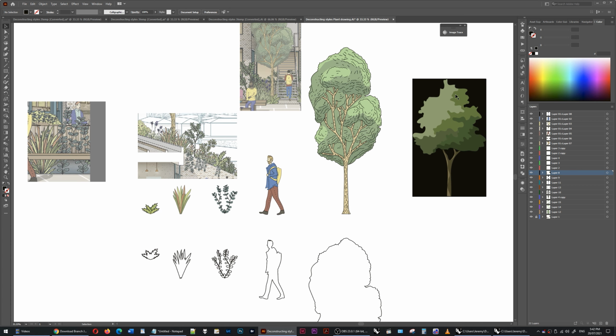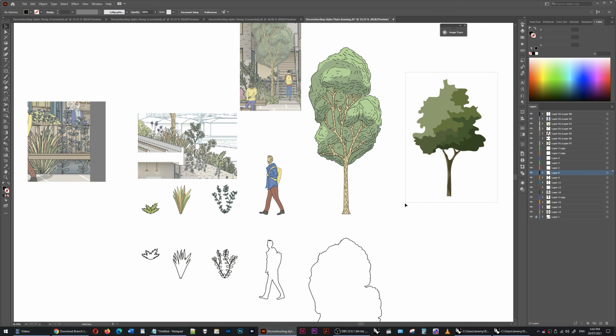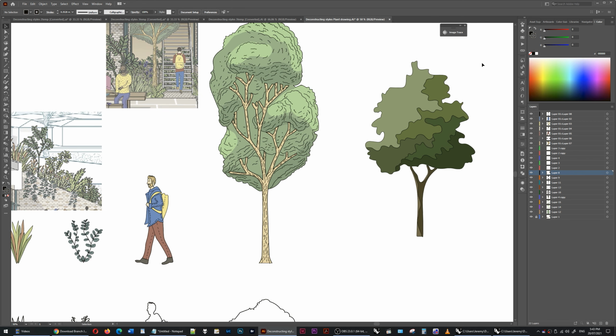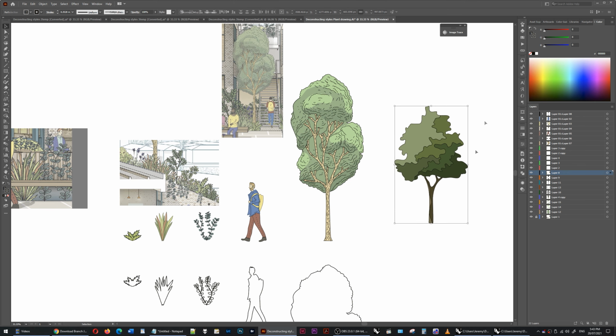You could even take an image from the internet like this PNG and do an image trace, expand, Control-Shift-G to ungroup it, deselect, select the black and delete, select those elements, create a black outline. Now you have a vector graphic. But it doesn't really matter because what we're importing into Rhino is a raster image anyway. So you can source the image from anywhere, so long as you have the outline curve, which you can create in Rhino, to cut it out as a stencil.